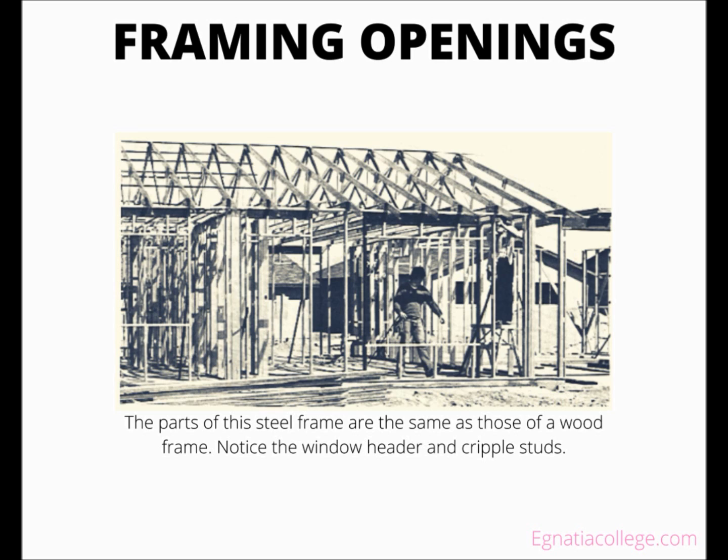Headers over openings in light gauge metal framing are usually very similar to those in wood framing. However, the system designed by the metal framing manufacturer should always be followed.